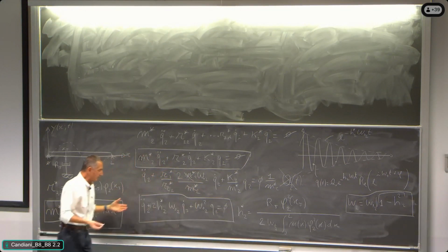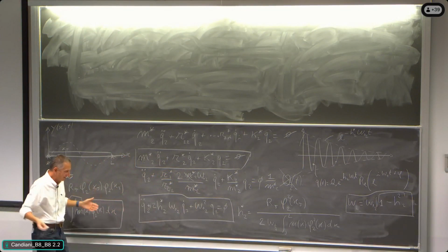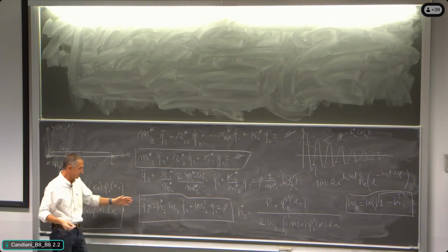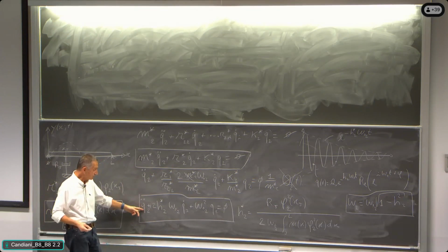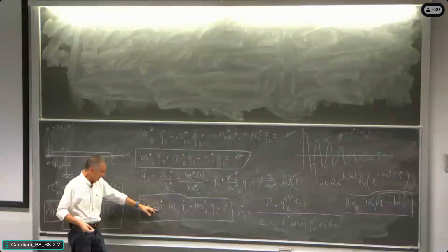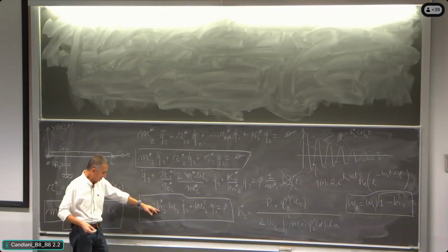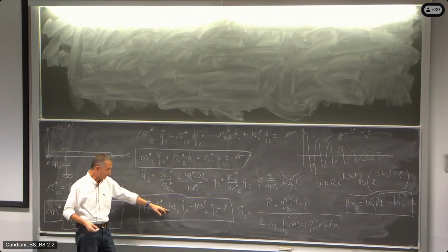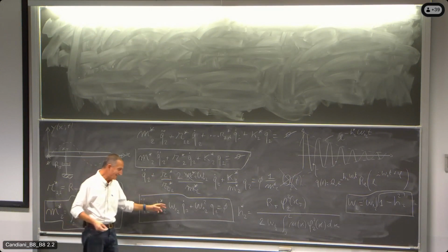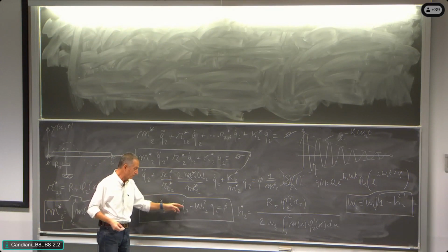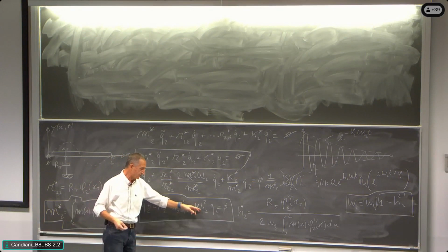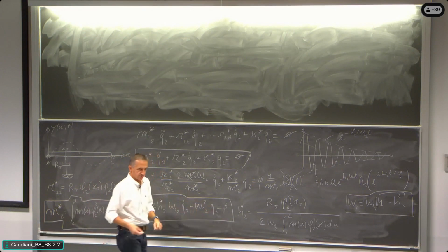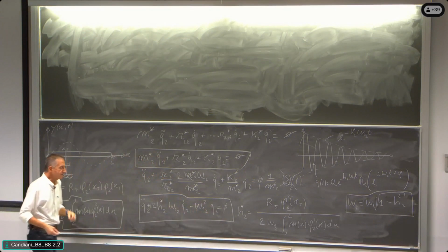And so finally the equation, of course, I think most of you know perfectly, is written in this way: q double dot 2 plus 2 times the non-dimensional damping associated to mode 2, multiplying omega 0, the undamped natural frequency of mode 2, q dot 2, plus omega 0 squared q 2. And that's it, it's finished. All right. So this is the equation.